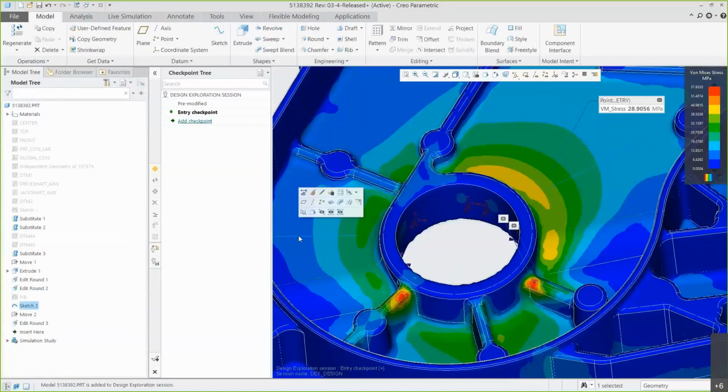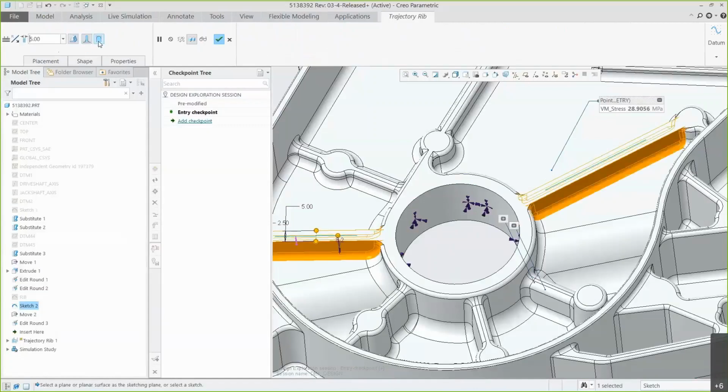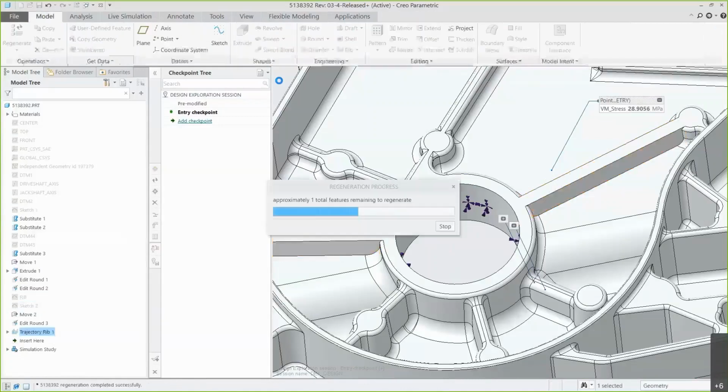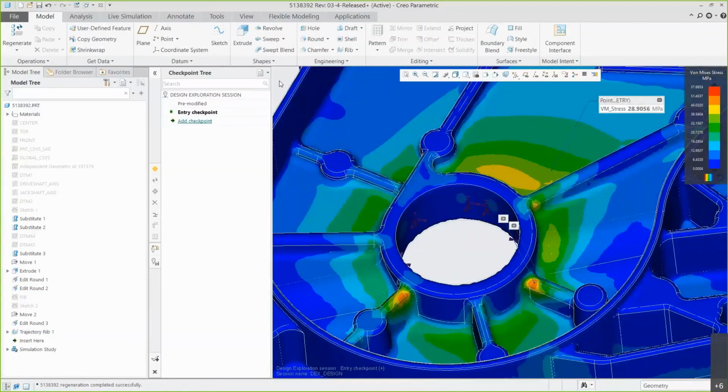And again, what we're doing here is just standard Creo work. This is just your standard thing that you would do on any given day-to-day basis. Going through, doing extrudes, making rounds, whatever it is that you'd be doing normally in your design process, we're not changing that. It's still staying exactly the same. But as we're doing that, we're getting that instant insight into saying, what does that do to my von Mises stress? Does it shoot it up? In this case, no. It's only going up from about 29 to 32.6.